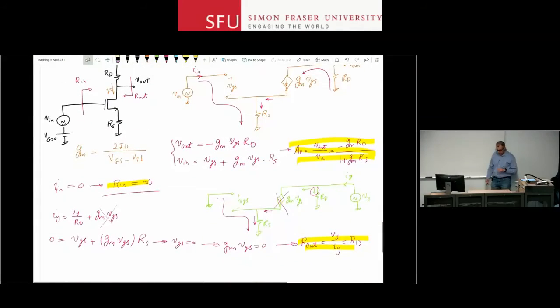In fact, I can see that the MOSFET circuits are actually easier to solve than the BJT circuits because, for example, when I look at the relationship between the drain and source, the drain and source currents are always the same. In a BJT, you have a contribution from the base that is going to show up in the emitter current. For a MOSFET, it's just drain and source. They're always the same current. Therefore, my equations are usually a bit simpler.